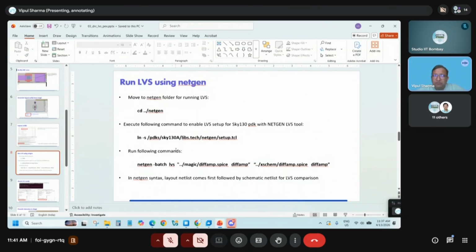For the small designs, since the areas and the sizes are small, we do not expect the connections or the nets which are made to have very big parasitics. So even if you are able to complete your steps till this stage, I think that's okay. Parasitics won't affect the performance of your circuit too much.